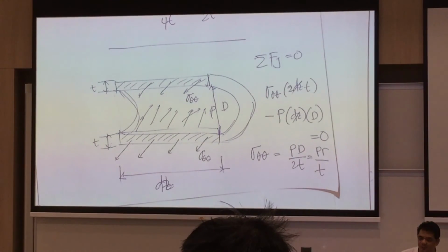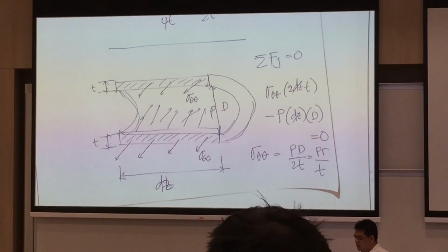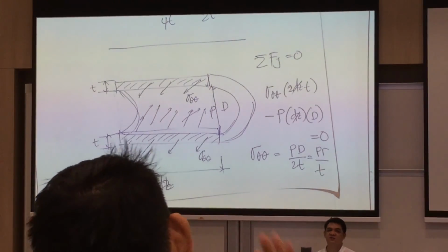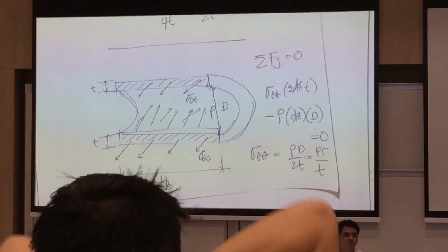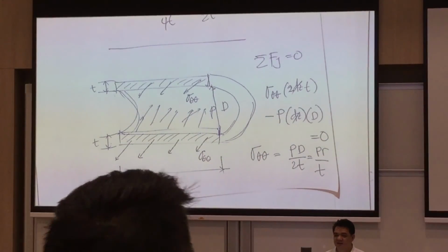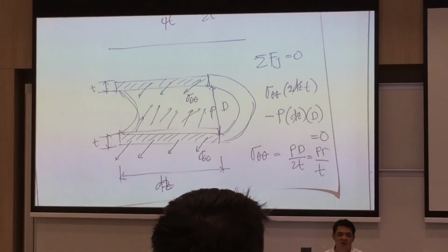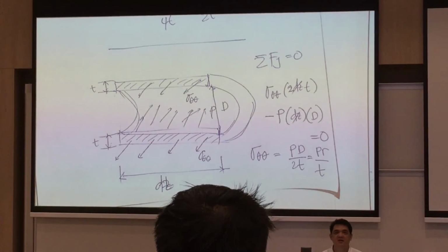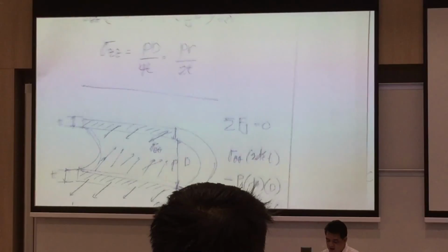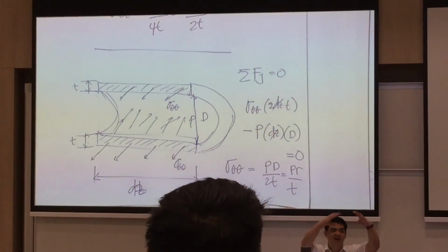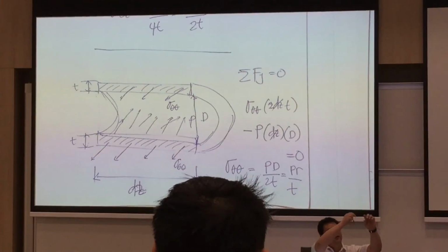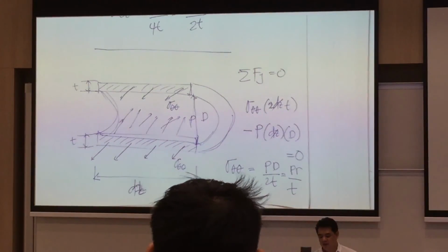Derived using first principle, no magic here, no analysis here. Of course, we haven't gone to the thick pressure vessels yet, which we will be going to later. Don't worry about that. That's where your small element will come in again. So let's have a look at this one here. You have your hoop stress acting around the hoop, and then you have your longitudinal stress acting about the neck of the pressure vessel.